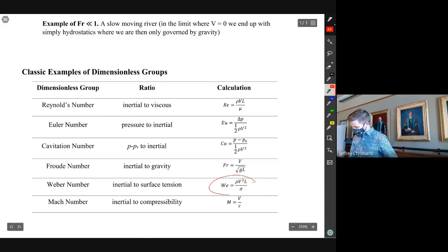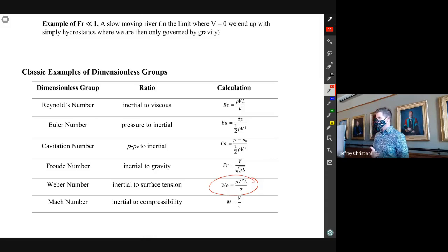The Weber number. If you're looking at, say, a pumped hydro system, surface tension of water has nothing to do with what's happening. It doesn't matter at all. You can totally forget it. None of you have started to try to incorporate surface tension into the models of what's happening, and that's good because it doesn't matter. If instead of a really big pumped hydro system, you were trying to look at, say, a really thin film of liquid, then surface tension actually probably is important.